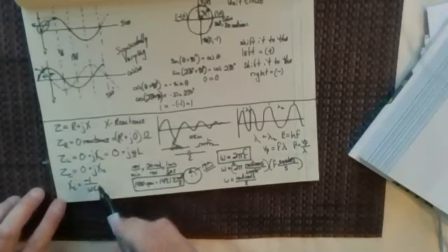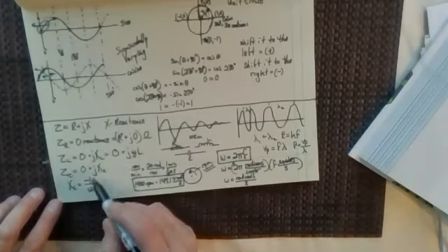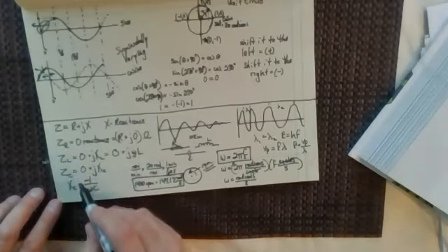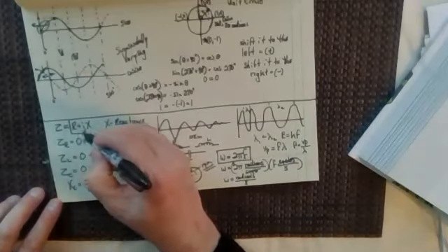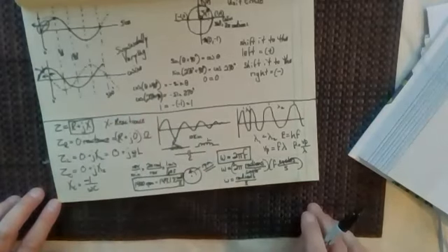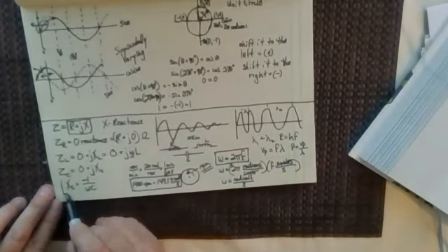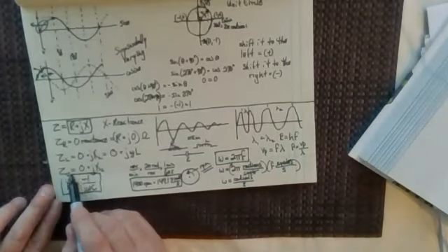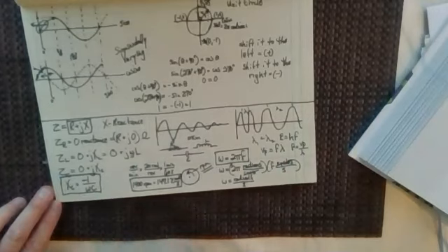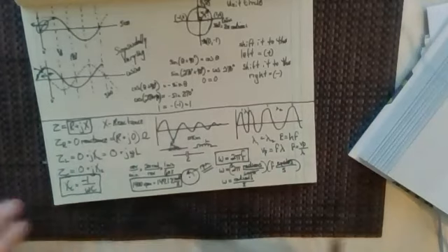And the minus is really in the reactance, I believe, rather than changing this. We should always keep this the same. The definition of impedance is R plus jX. So we should always have that plus there, and then we should keep the minus in the reactance, 1 over omega c. And now we'll get into that.